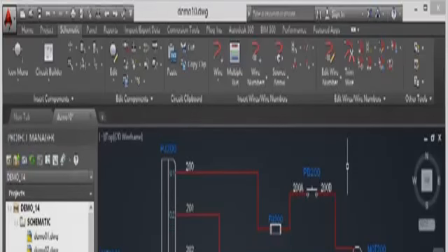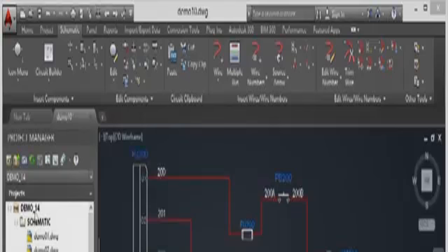You can also add an existing circuit into the icon menu in AutoCAD Electrical. Now we're staying in the Demo 14 project and we're using the Demo 10 drawing. What I've done is I've zoomed into an existing circuit in the Demo 10 drawing to use as the active view for the icon that goes into the icon menu when we actually create it to go into the icon menu in a moment.